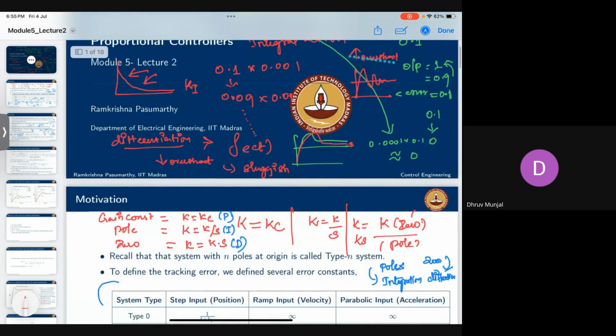So you should be able to know what proportion you are using for each and every controller. How well you are tuning this KP, KI, KD depends on you. There is no predefined book rule for how you are going to choose the KP, KI, KD gains for your system. It's a trial and error method. There are some concepts like the Ziegler-Nichols method for tuning this KP, KI, KD. But for most of the simple systems, tuning by hand would do.